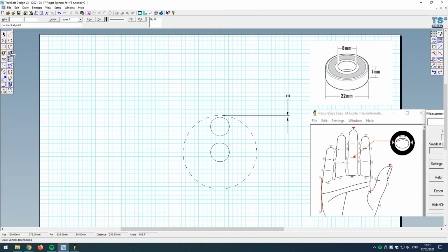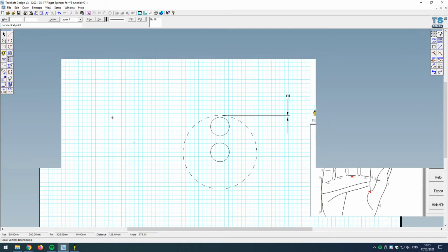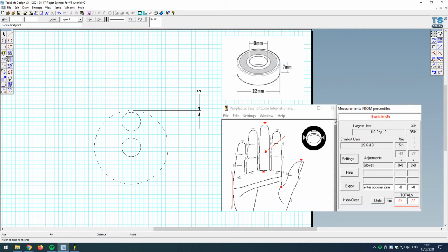Okay, so in that particular case, I'm thinking now that, with regard to the development of my CAD file here, if I come to the circle tool again, I'm going to go for a 13 millimeter radius, which is 2 millimeters greater than 11. And I'm going to imagine gridlock on again. I'm going to pop that there. And I'm going to imagine here that that might be, let's delete that dimension line.